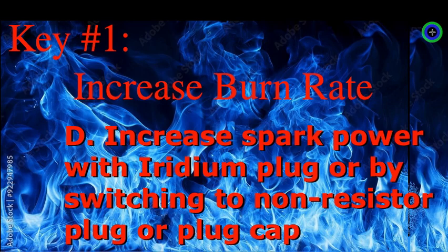Given that the power, which is the voltage multiplied by the current, is the same from the high voltage coil, then if you reduce the voltage requirement at the spark plug, you automatically increase the current that's happening at the spark. The more current, the hotter the spark.